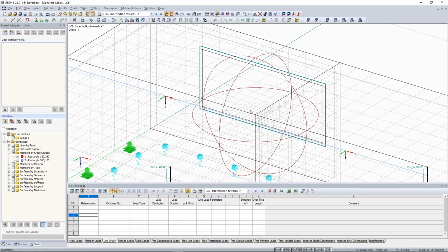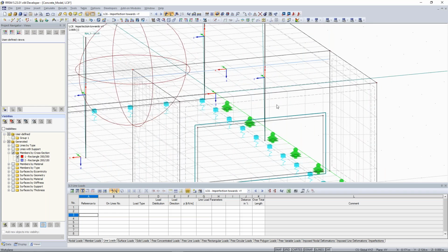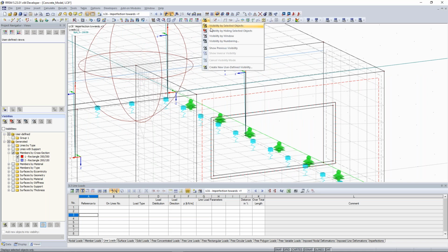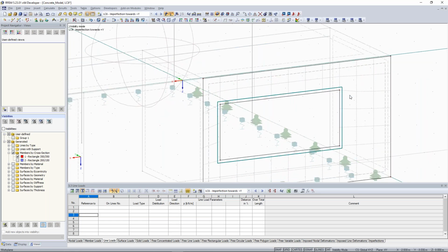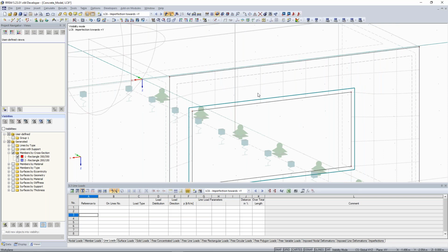For example, I learned it in that way, that at least here you need 4 FE elements in order to have good results at this surface here. So when you want to interpret some internal forces or some results, I don't know if 2 FE elements are enough in order to get good results. It's up to you.